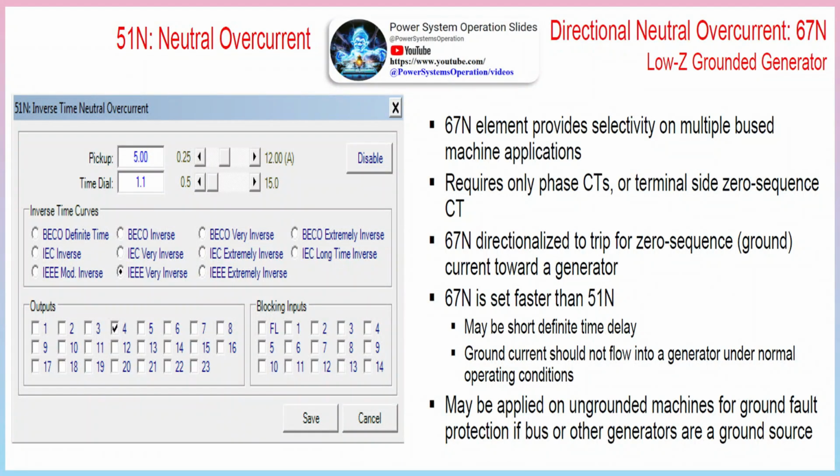Generator capacitance and third harmonics. Third harmonics are produced by some generators, the amount typically small, with lumped capacitance on each stator, CS divided by 2. CT is added at the terminal end due to surge caps and the isophase bus. The effect is that the third harmonic null point is shifted toward the terminal end and not balanced.